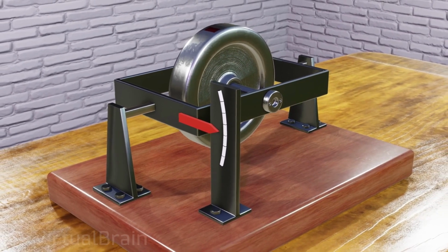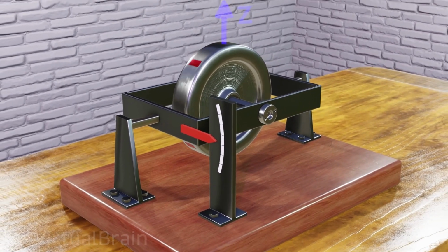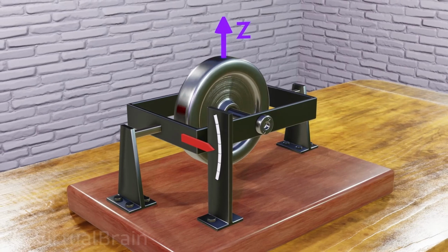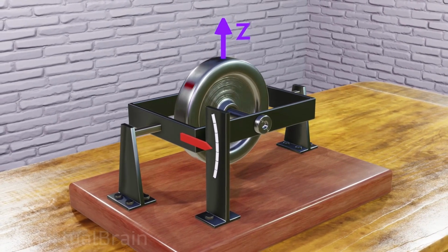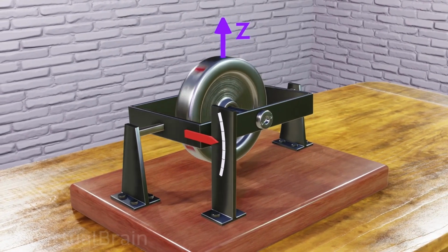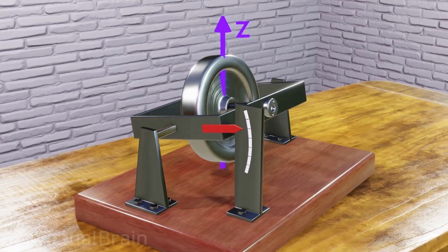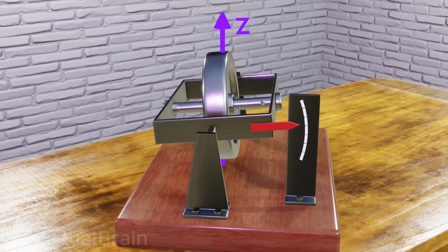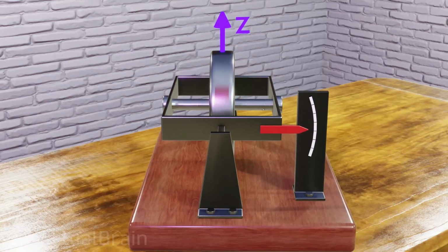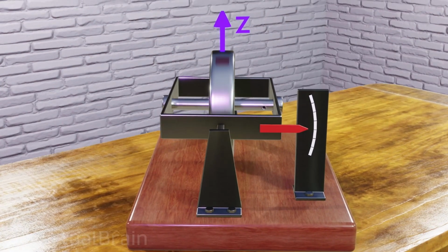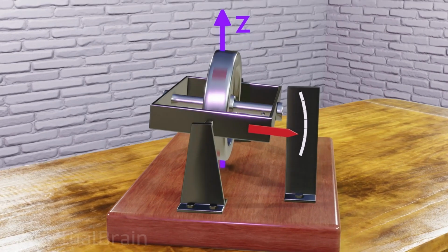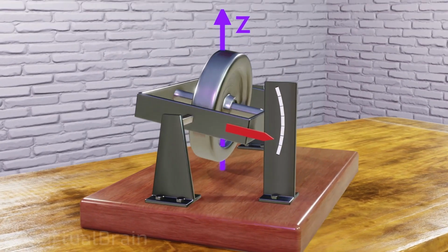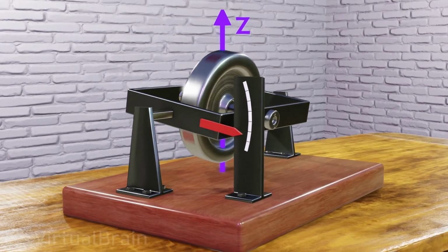This particular system is made to detect movements in the z-axis. If the central disk is rotating, and the whole system is rotated about the z-axis, the precession will generate a torque on the torsion bar and the frame will rotate slightly, marking a value on a conversion scale, allowing the angular velocity of the system to be known. It's not the most intuitive system in the world, but that makes it even more impressive from a design standpoint.